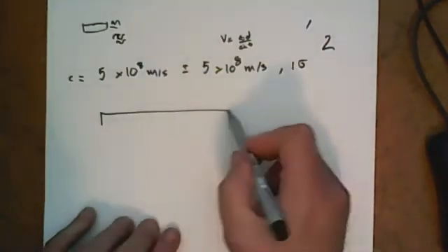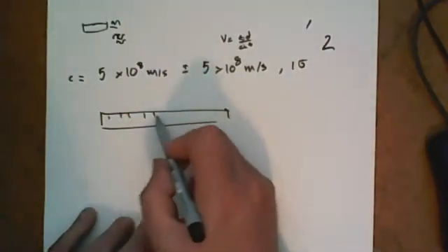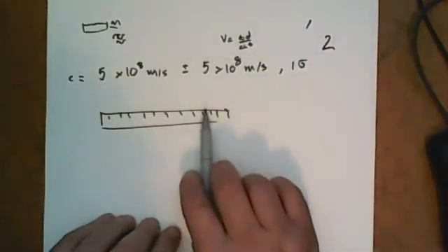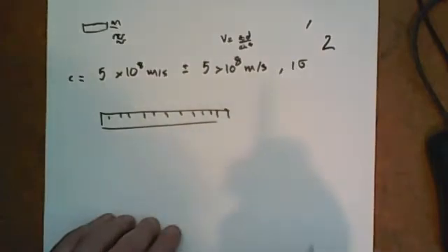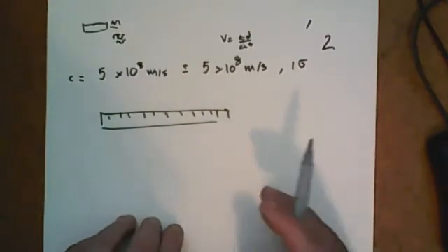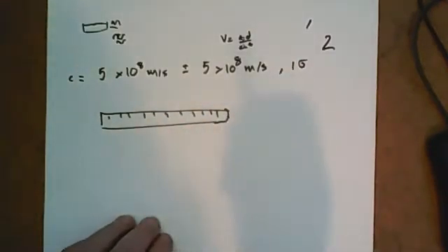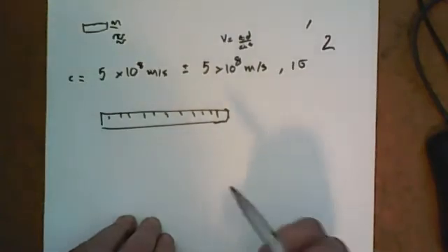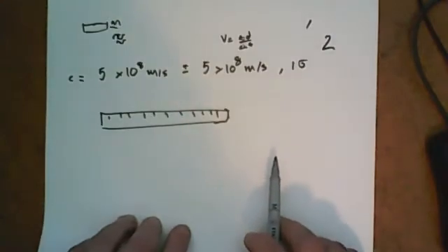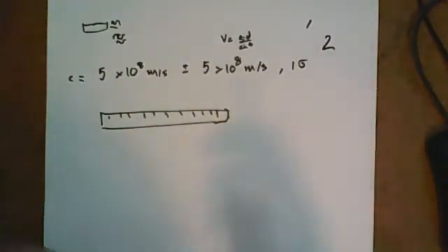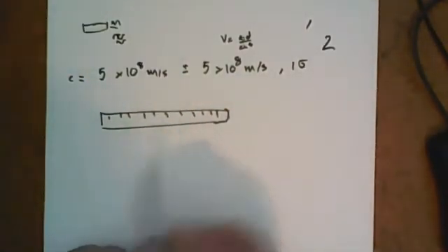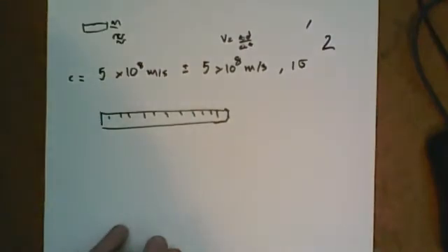So if I grab a ruler and it's got all these little marks, sometimes the things I'm going to measure are going to end up between them. So what's the most accurate that you can measure with a ruler? It's usually plus or minus half a mil. And this measurement of anything that you're dealing with becomes quite important, especially when you add in things like expansion and contraction of systems. And this partly goes into your safety factor.